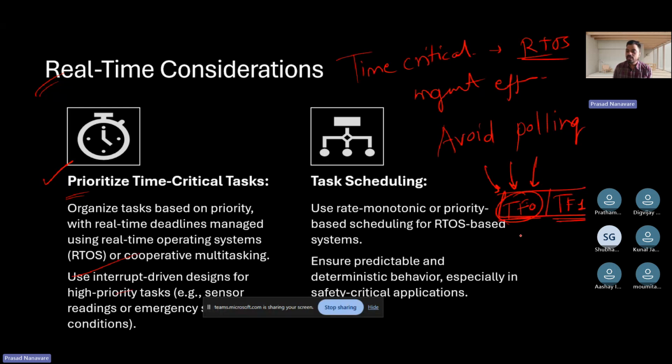We were waiting in the code until this is set. That is called polling. The standard practice definitely does not recommend polling. At our level it's fine, but at enterprise level it's not fine. So you should implement an interrupt based mechanism in order to address such issues.